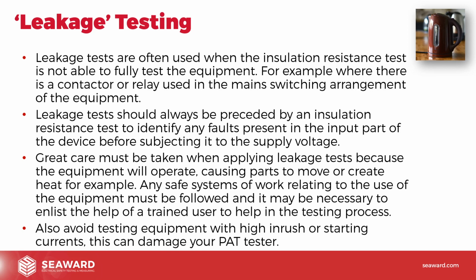So always think about the duration of these tests, how long you're going to apply the tests for, because you need to apply the test for a long enough period of time to test consistent operation and to test the equipment in all its different modes of operation as well. So always apply the test for the right duration. Don't just think, how quick can I get away with this? Because you might not actually be allowing the equipment to fully operate, and you're not going to find faults. So actually you're just doing a pointless test there.